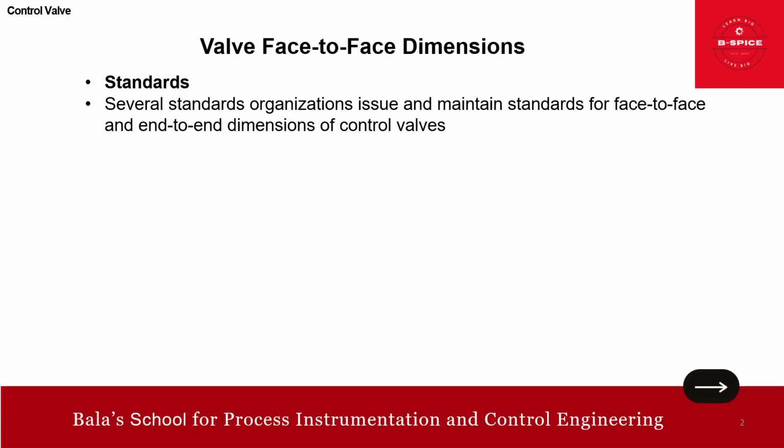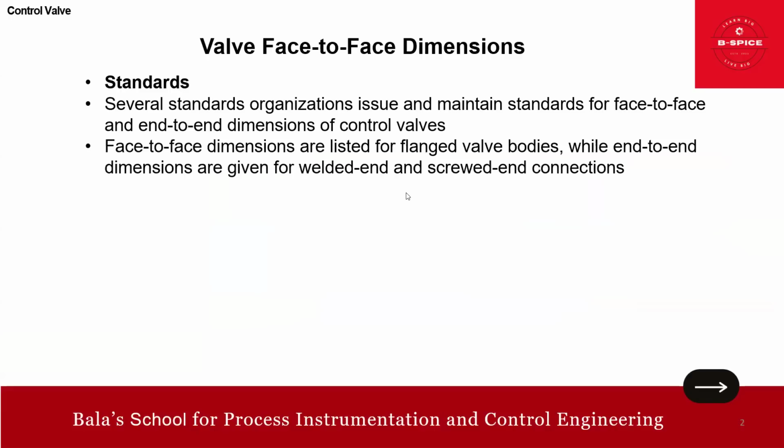So what are all the standards? Basically, we know several standards organizations issue and maintain standards for face-to-face and end-to-end dimensions for control valves. Face-to-face dimensions are listed for flanged valve bodies, while end-to-end dimensions are given for welded-in and screwed-in connections. Just remember that.